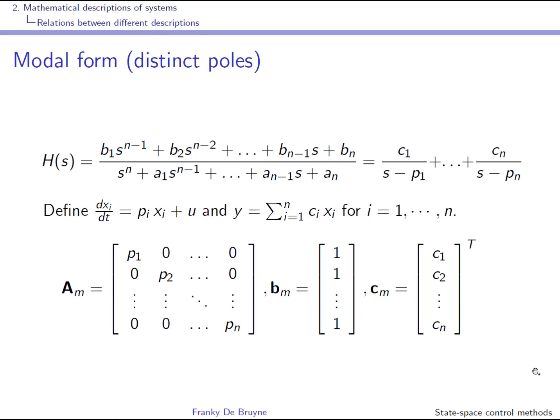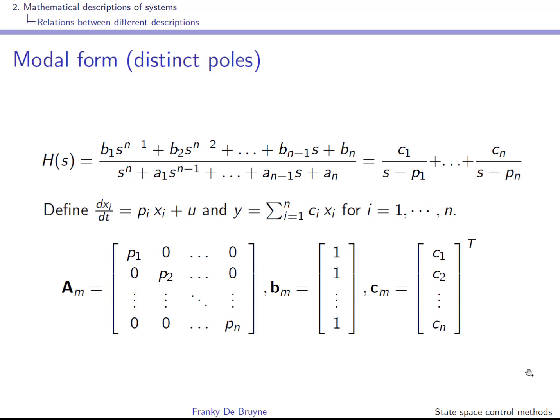Well, as you might have noticed, I have skipped a few slides that are there for your information, and those slides contain the controllability canonical form, the observer canonical form, and the observability canonical form. Those are different canonical forms that can be used to implement the transfer function h of s that you see on the screen. Well, one form that is important is the so-called modal form.